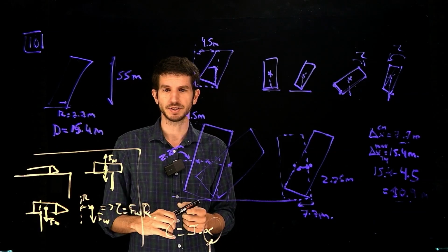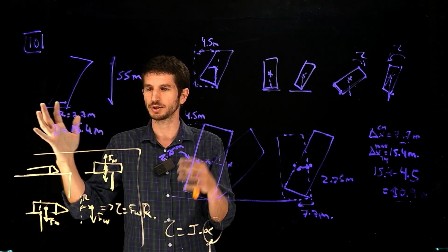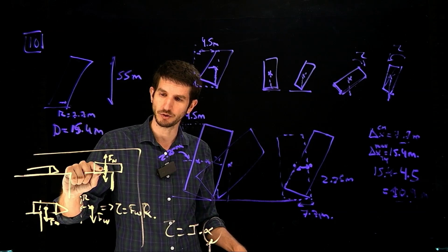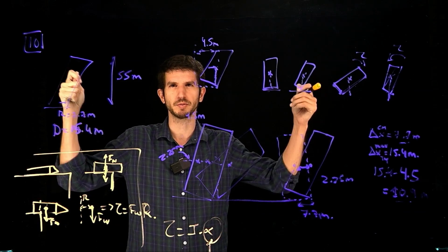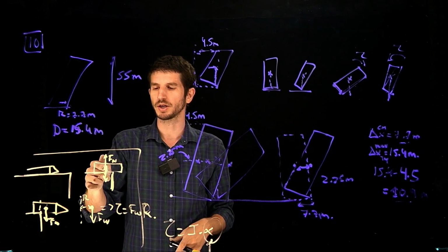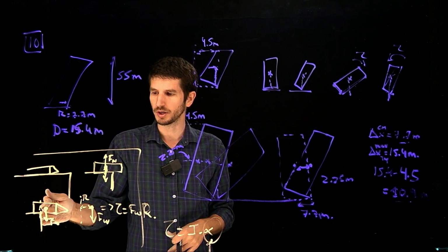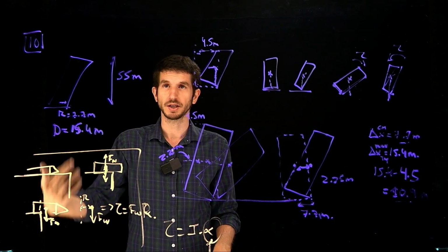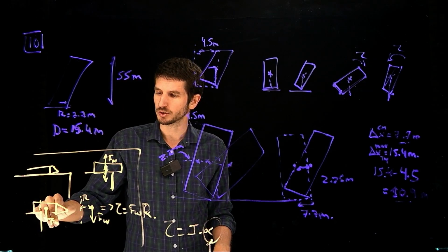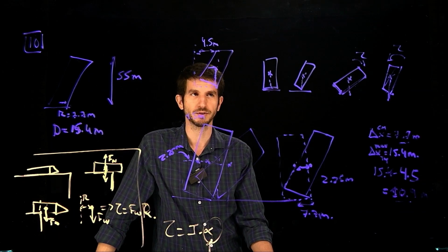Now we can see the idea of stability here, based on the equilibrium conditions: vertical for translational in this case, but also torque in terms of rotational motion. As I push the pen, the center of mass is all I care about, because there's no single object, not like with the beam where we were applying forces. The only force here is the weight, and weight is sustained as long as it is over the base. But as soon as the weight goes past the edge of the table, that weight is producing a net force without any counterbalancing force. It's producing a torque, and that torque is going to be responsible for rotating that thing, and it tips over. That's the idea here of stability.